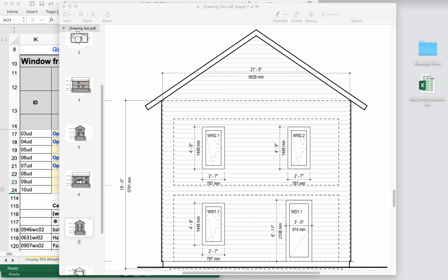For the most part, the window units are pretty straightforward. We've got tilt-turn windows, no mullions on this side, which is great. But we do have one new window type or door type that we want to model in here. So we have to build one last frame type, and then we can finish off all of our window elements. The new frame type, of course, is for our swinging door.